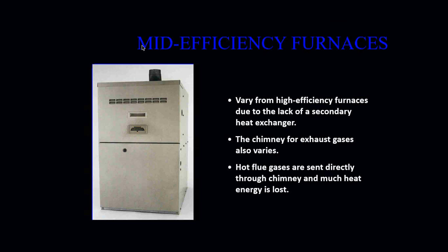Your mid-efficiency furnaces are going to vary from high-efficiency furnaces due to the lack of a secondary heat exchanger. Our older style furnaces may only have one heat exchanger, and with only one heat exchanger, our efficiency greatly drops. The chimney for exhaust gases may also vary. Hot flue gases are sent directly through the chimney, and much of the heat energy is lost. The more heat that we lose through the chimney, the less efficient the furnace is.